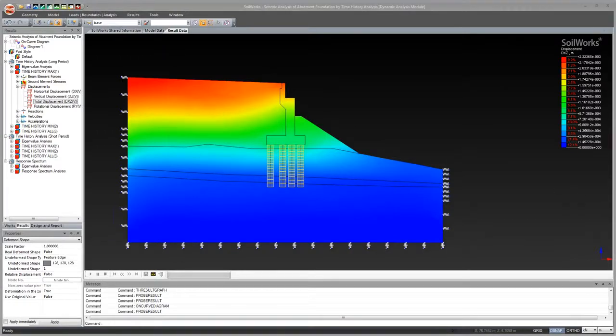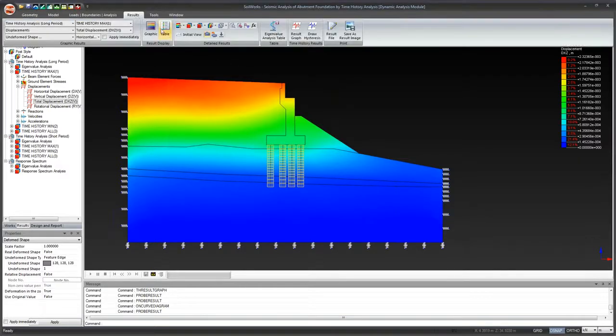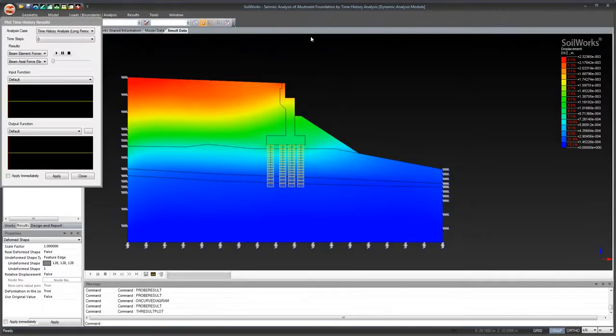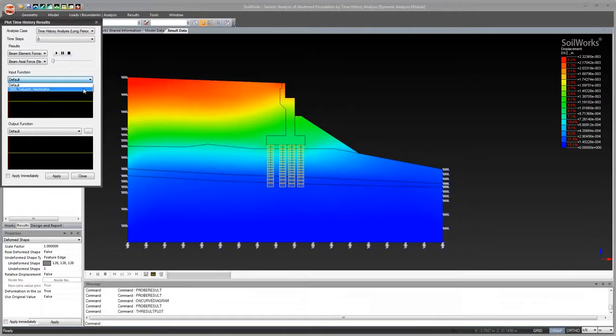And then, for those of you who want to draw your time history, so for example, let's say you want to see how the results change specifically at which point of the earthquake, or along the time history function, go to Results, and then go to Draw Hysteresis. Go to this function here, and make sure to select your time history function. So let's select our first set, and let's not select the axial force, but the vertical displacement again. And just use your mouse cursor here to move this along the length of the earthquake.